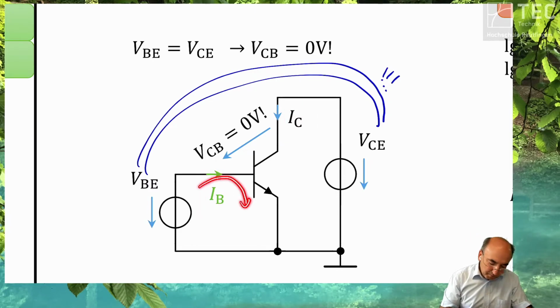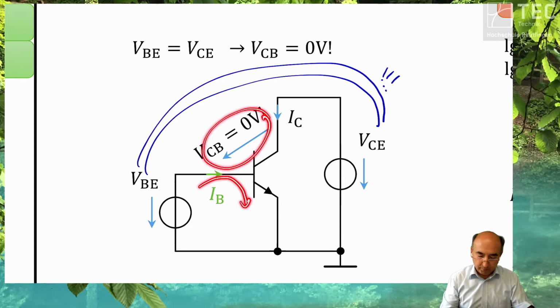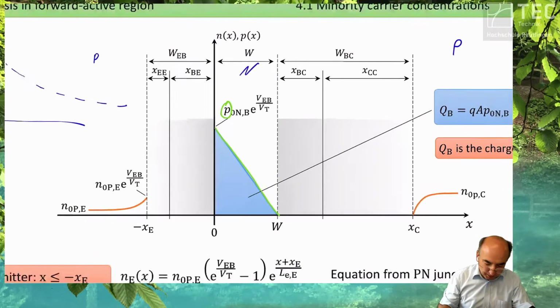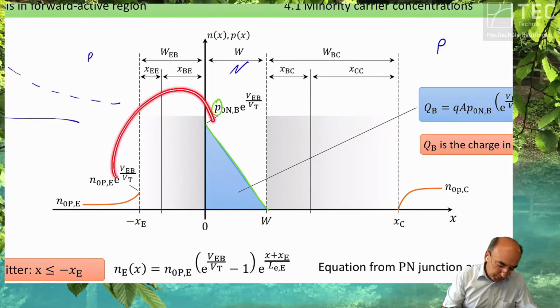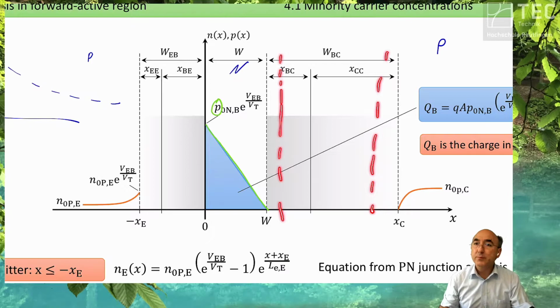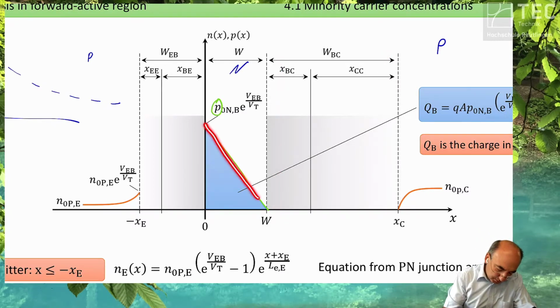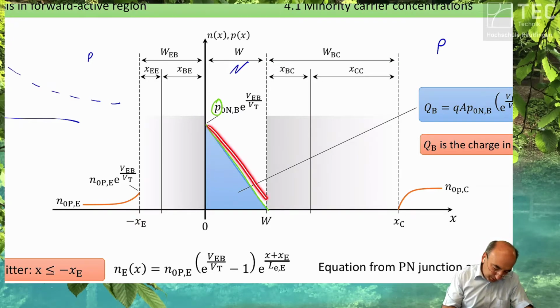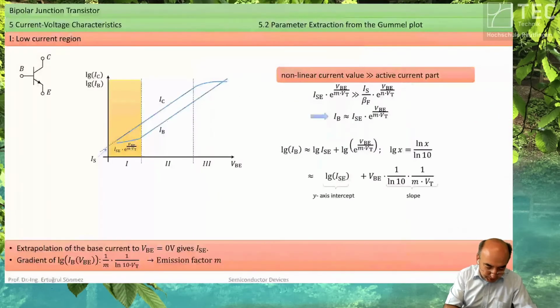So if you inject a base current and if you don't apply any reverse bias, what condition do we have? We inject majorities, here we are, but we don't apply any reverse bias. So the space charge is, let's say, here, and this point is here, and this point is the p0 in the N region. You remember? Go to the page 59 or something like that. The minority carrier concentration is then the natural value, but not zero. Okay, so that's the only difference. So the Gummel plot plots this condition.